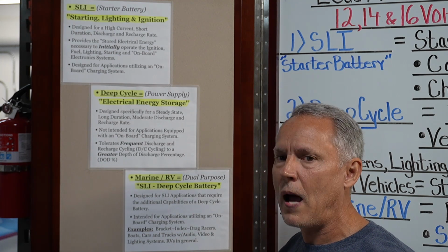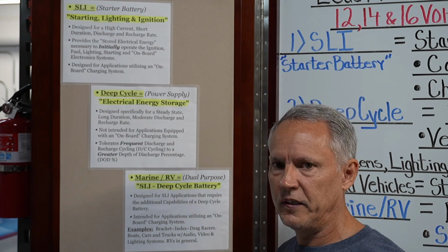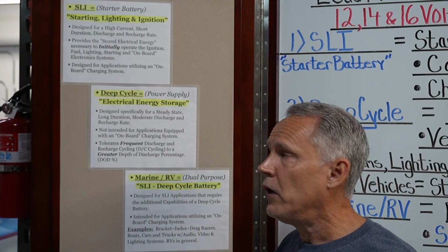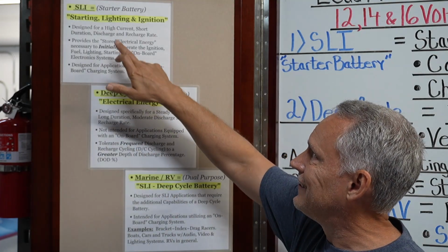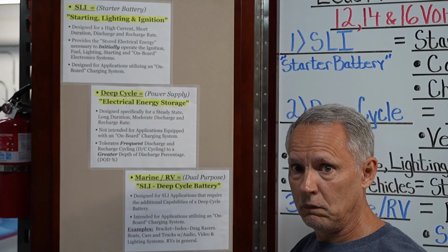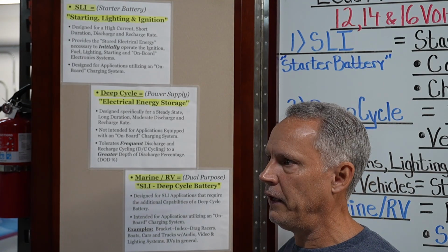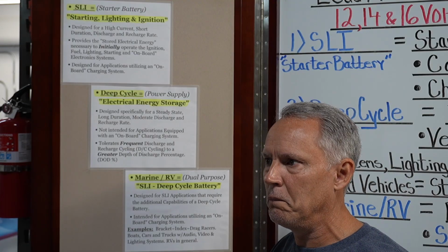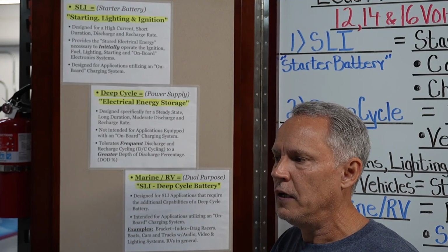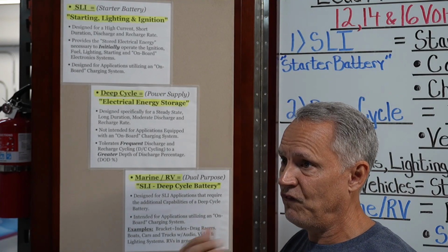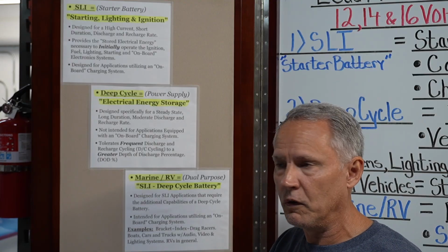It has to be done rapidly so that the battery is not really discharged the entire time you're driving the vehicle. So that being said, it is designed for a high current, a lot of draw, short duration. The starter motor itself, in most cases, it's seconds. It could be 2 seconds that you're actually starting the vehicle. It could be 15 seconds, hopefully not, but it could be as long as that.